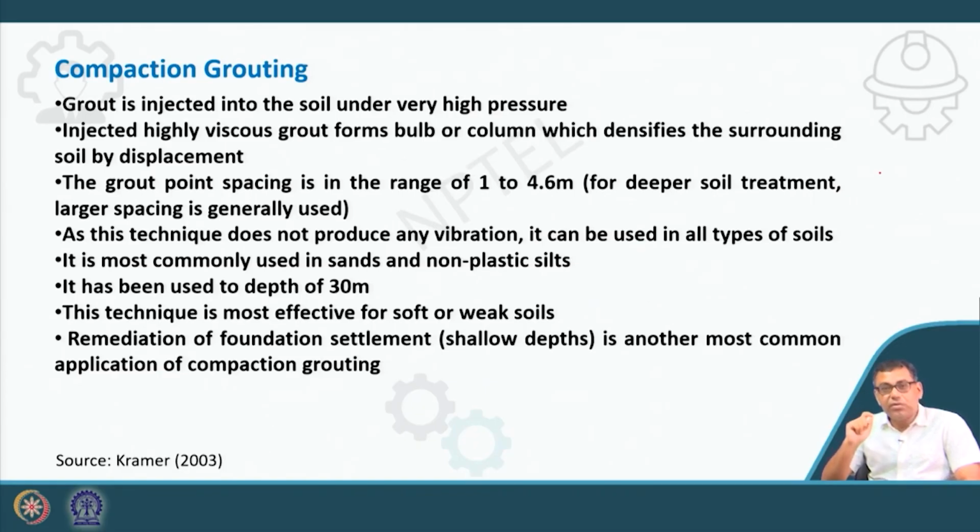And the last technique for this compaction is compaction grouting. Okay. So, grout is injected into the soil under very high pressure. The injected highly viscous grout forms bulbs or columns which densify the surrounding soil by displacement. So here a grout material is injected into the soil at very high pressure, and this injected highly viscous grout forms a column, called the grout column, bulb or column, in the soil. That will displace and densify the surrounding soil.